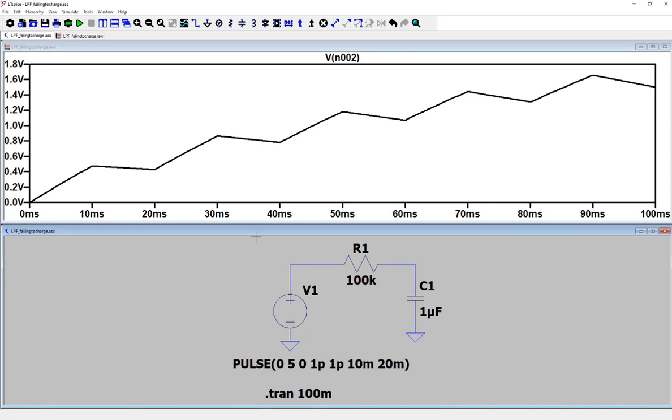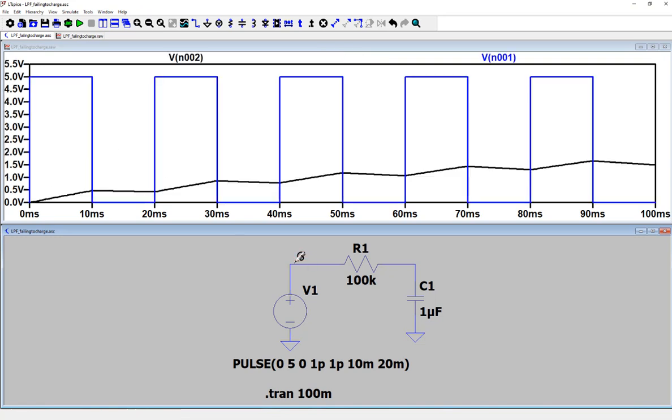Since I told you last time, if you have a low pass filter and you have a pretty fast oscillation, so the oscillation here is considered pretty fast, okay? You can see, even though it's not that fast, compared to these RC circuits, it's fast. So this RC circuit has a pretty big time constant. So your digital oscillation here is not able to fully charge and discharge the cap through this resistor because the resistor is too big or too small. And why? Too big.